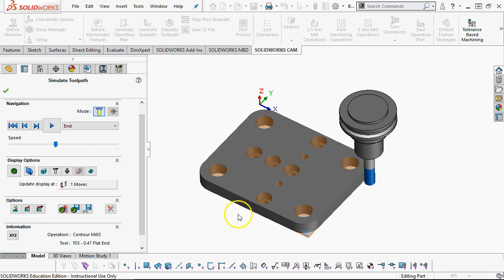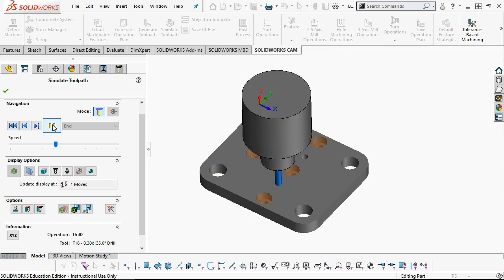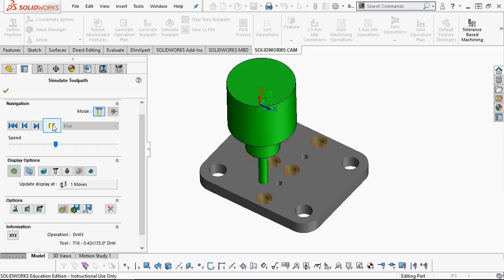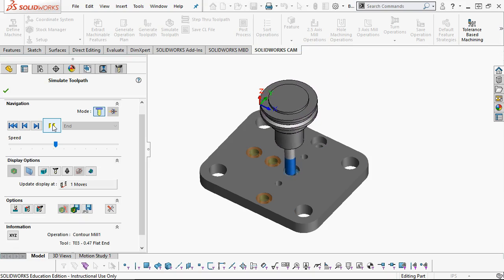And then as we go around the outside, not that we really required perpendicularity on this one, it's the rigidity of the tool, the accuracy of the setup that is producing our perpendicularity going around the pieces. And then the drill and ream, that's what's going to provide our positional, and that's within the capabilities of the machine to make from part to part or even on the one piece.